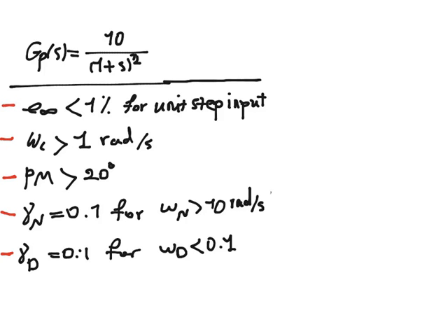However, by setting the proportional controller's value to 1, by simply forming the unity feedback, we had seen, referring to the Bode plot of GP j omega, that we had cutoff frequency bigger than 1 radian per second, phase margin bigger than 20 degrees, and the requirements on the attenuation of the noise were already satisfactory.